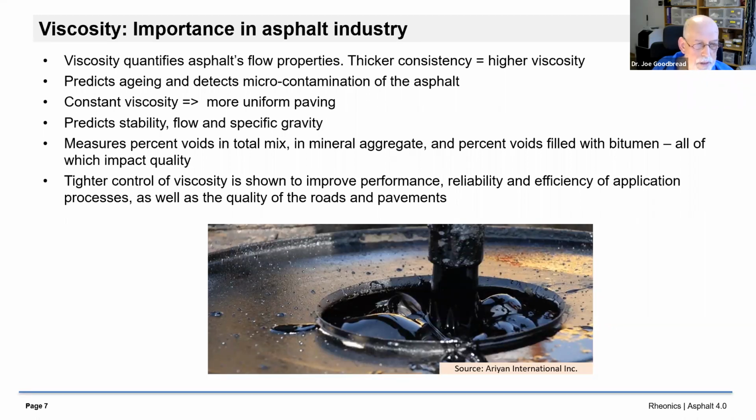These flow properties, and therefore the viscosity, are useful for predicting how the material will age, as well as helping detect contaminants in the liquid asphalt. Since viscosity measures how the liquid flows, constant viscosity means more uniform paving. Viscosity can predict the material stability, as well as giving insight into its composition.